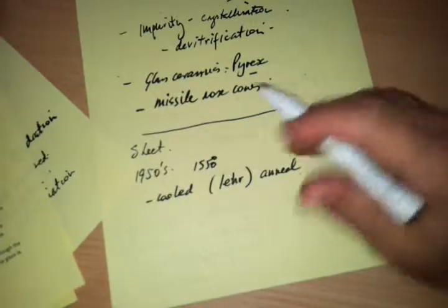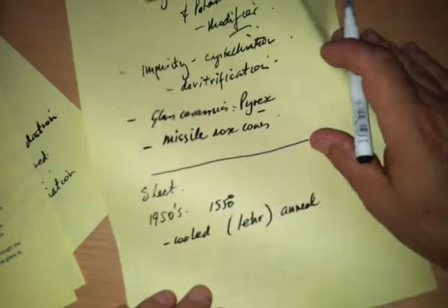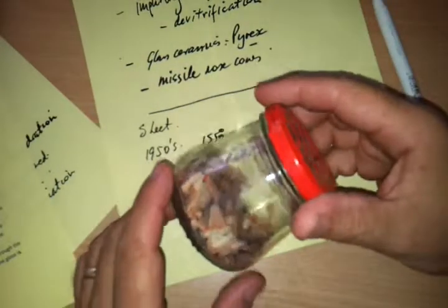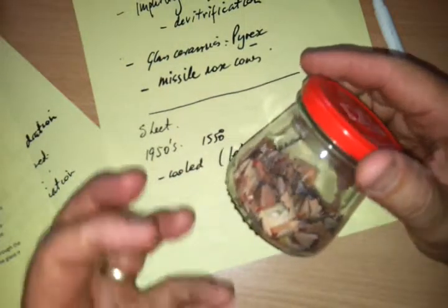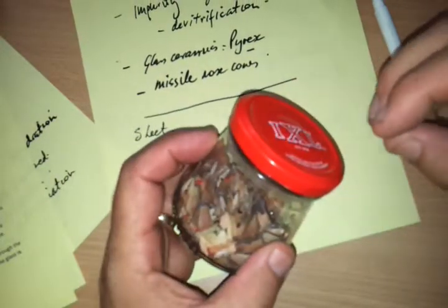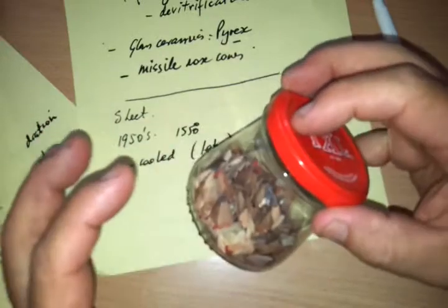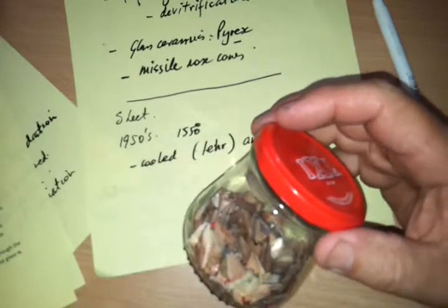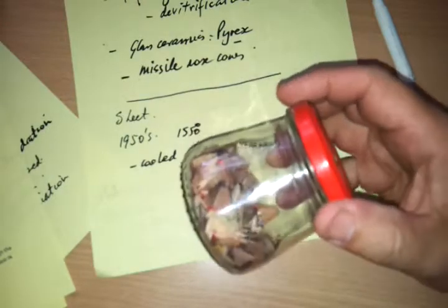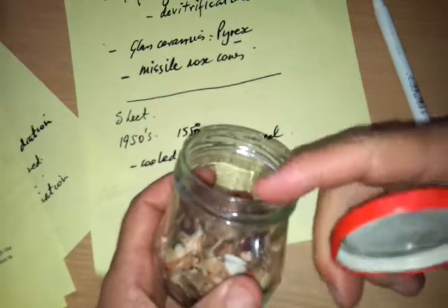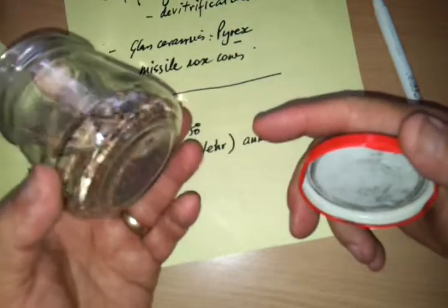When you're creating a glass container, for example, like this glass container over here, a gob, or just a single big lump of glass, would have been put into a mould. Compressed air is blown into that mould, forcing the glass onto the outside of the mould, creating the shape that you want. And this is then cooled to relieve stresses at the appropriate temperature. So that's to create shapes like the one that you see here.